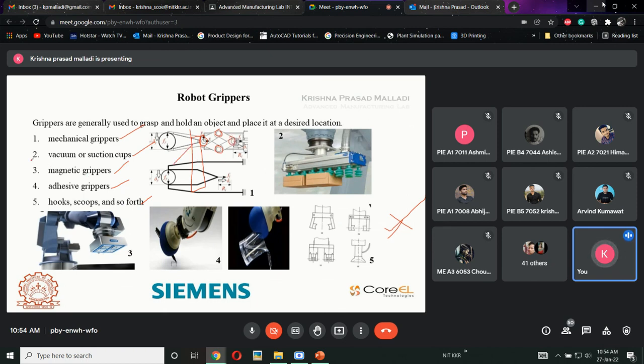If you are using vacuum or suction, which means you are using a compressor, pneumatics, then these are the type of grippers that we'll be using. They are going to inject air there, and then automatically reverse suck it, so that the part will automatically be picked up. If I pick these cardboard components with mechanical grippers, then what will happen? There will be a hole, a dent that will be formed on this one. So that is vacuum.